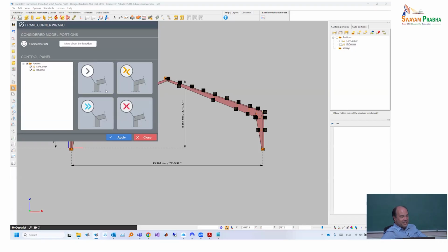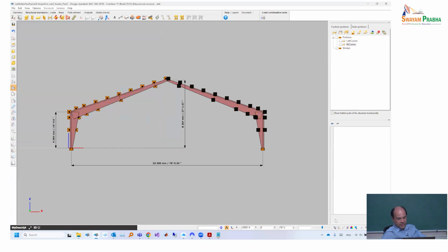So you select these two elements, and you select the very first at the moment. If you do, this works in a very complicated way. Then you are supposed to see a box which represents the corner zone. Now, if you don't see it, there are several reasons. You made something wrong, or just the visualization is switched off. If the visualization is switched off, then you will never see it, even if you did it well.